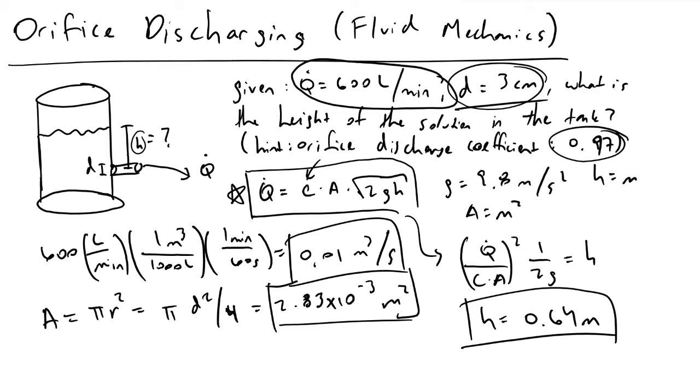So you could very easily design some kind of process controller, like a PID controller, to regulate some kind of input into this system in order to keep things constant, to keep your volumetric flow rate exiting your reactor constant, or the height of water about some kind of value that you're interested in.